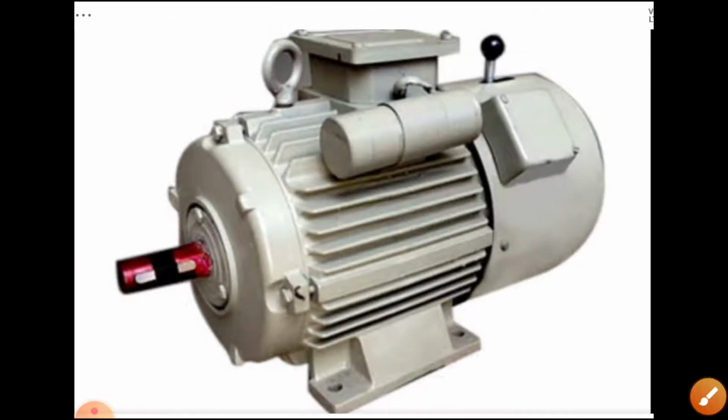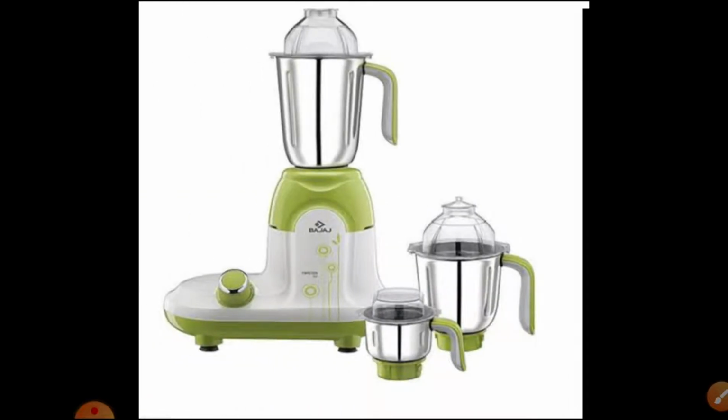Okay, so these are all single phase motors generally observed in our domestic applications, in pumping the water from the municipality water sump to our overhead tank. And you can see this is one application of the AC machine. Generally used in our domestic is a mixie, and inside there is an AC motor. This motor has the commutator and brushes also, but it can operate on AC as well as DC. Hence we can say the inside motor is a universal motor, a high speed motor, 3000 rpm it can run.